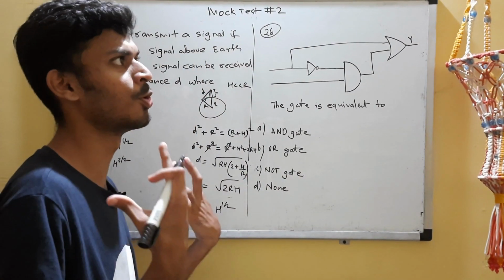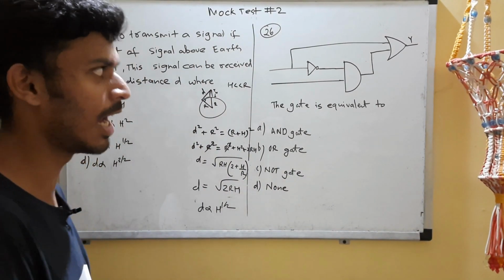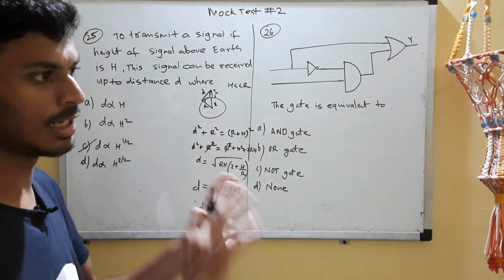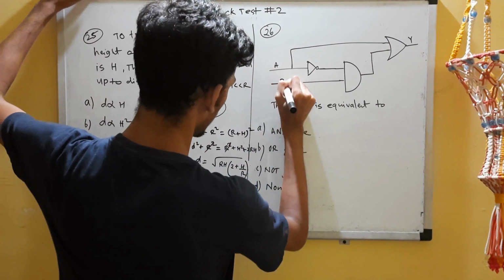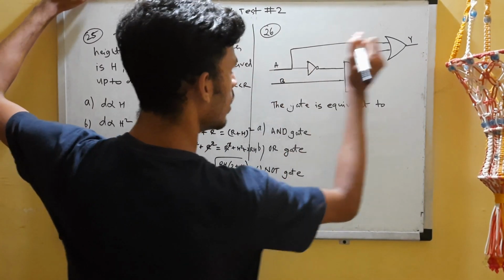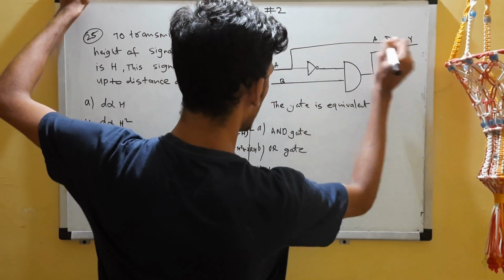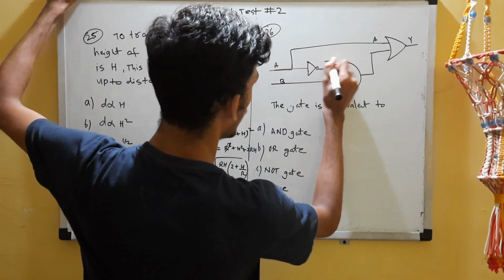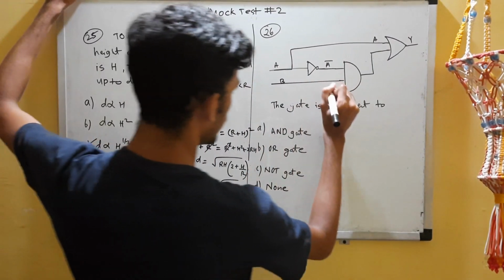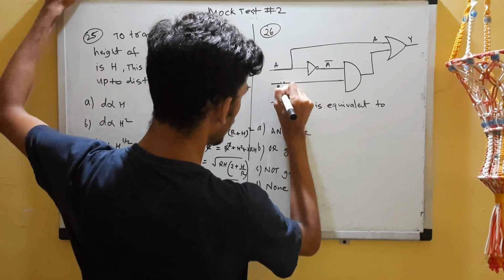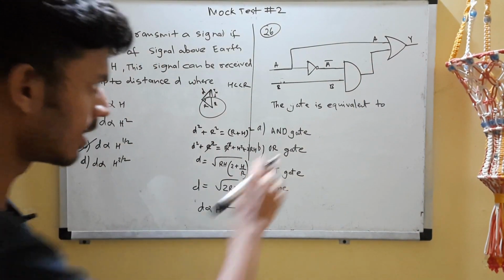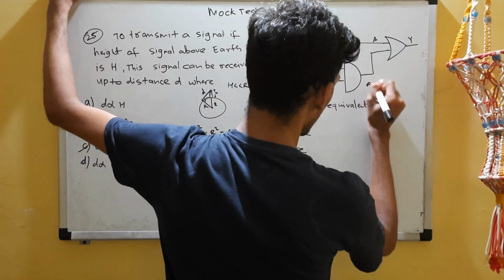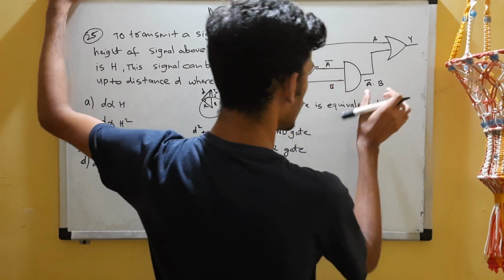I also don't know a lot of Boolean algebra, but I'll do it. I'll manipulate it using sets. I'll come to that. So let's begin with A and B over here. The signal A is going, so here also we'll get A. And here we'll get not A, A bar. And here the signal is B, so here also we'll have B. Now not A and B are going in. This is an AND gate. AND gate just multiplies the inputs. So this is the output.